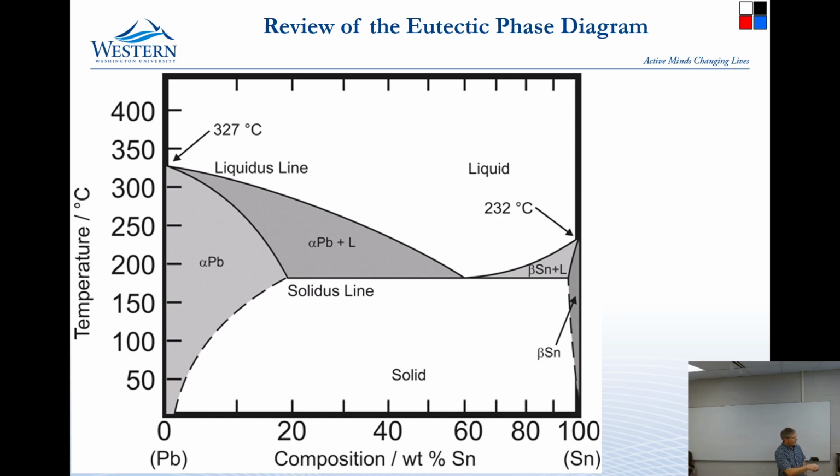The understanding that if you move temperature-wise from one place to another, even with a material that is solid, it can change what it looks like inside. We're going to talk more about that later today. And then it's also important to understand that there are these slushy zones where there is a mixture of solid and liquid. And the slushy zones become really important in casting because next to the walls of the mold are going to solidify.